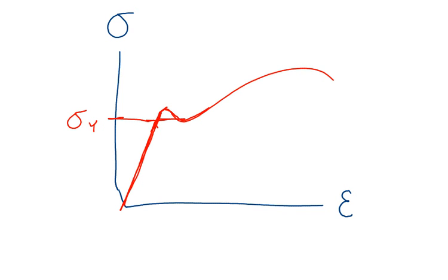Let's say I stretch my piece of steel all the way to this point on the curve. Okay? So I've gone all the way here. What happens when I let go of my stress is that my piece will try and recover, right? And it'll recover almost to its original shape, but not completely.